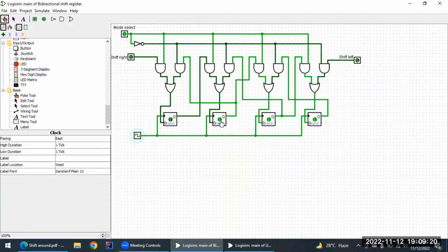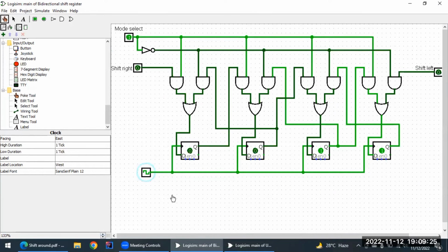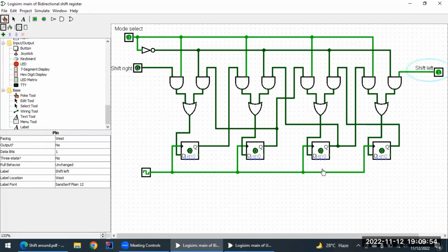I want to shift this value 0 to the right again. That's what happens. I'll zoom it in here so you can see it more clearly. I want to shift the value 0 to the right again. I do that. And again. So basically this and this input decides what value you want to shift right or left. And here 1 or 0 decides if you want to work with shift right or shift left. Now I'll prove this by showing you that currently it's on 1, which is shift right. The reason I say that is because no matter what I do here, nothing gets affected here. If I click this one, it's gonna simply work as shift right, not shift left.